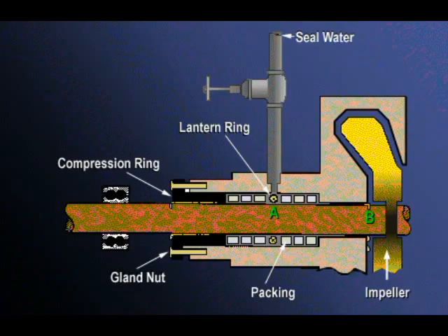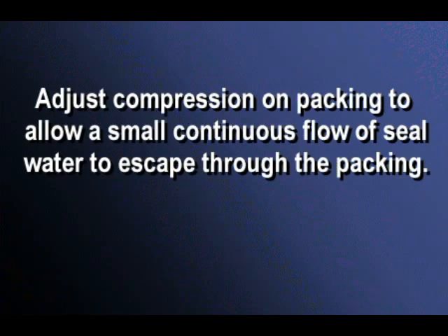Wastewater generally will contain abrasive particles which will damage and wear the shaft over time. As mentioned, the compression ring should be adjusted so that the packing is loose enough to allow a small amount of clean water for cooling and lubrication to pass, but not so loose as to allow a large flow. Every time an operator walks past this kind of pump, he or she should check for a slow drip and adjust the gland nuts as required to maintain this flow.